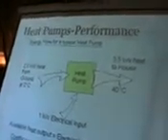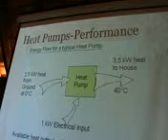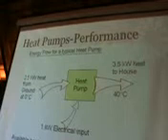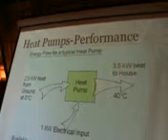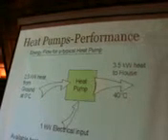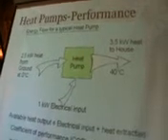So the overall sort of energy flow or power flow for a heat pump, you do need some electricity to run it. This is an example of a fairly small heat pump. So you put some electricity in, maybe a kilowatt in this case, and you collect, for example, 2.5 kilowatts from the ground, and the total output you get, in this case, is 3.5 kilowatts. So the electrical input and the heat input end up as heat output. So you're taking some electricity and you're ending up with 3.5 times, in this case, the amount of energy you started with, that you've collected from the local environment. So it's a sort of way of extending the energy you've got, the electrical energy.